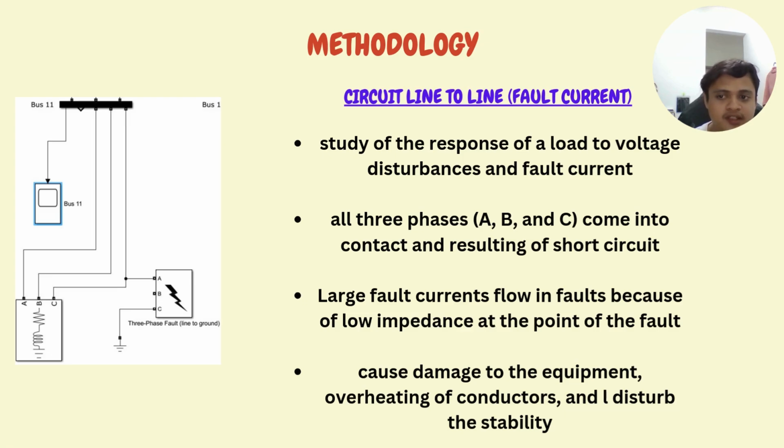The three-phase load block represents a connected load which has resistive and inductive characteristics with real-world behavior of loads. It permits the study of the response of a load to voltage disturbance and fault current. In a three-phase fault, all three phases A, B, C come into contact, which can be called a short circuit. This type of fault creates the worst-case fault condition. Large fault current flows in the fault because of low impedance at the point of the fault.